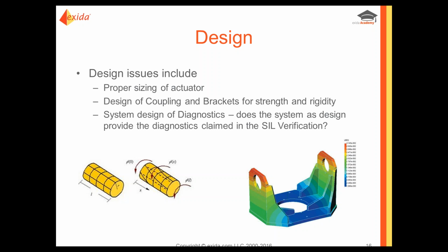How that happens is if you use partial valve stroke testing as a diagnostic, you can recategorize some of the dangerous failures from dangerous undetected to dangerous detected.